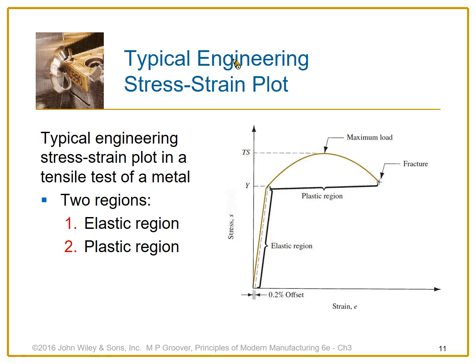And this is a very typical engineering stress and strain plot. It actually shows very interesting behaviors about materials. Let's take a look. You put the strain here, engineering strain, because we put an e, and this is the stress. As we know, this stress is F divided by A. And this is the elongation proportion, right? L minus L0 divided by L0. Then we see the curve.